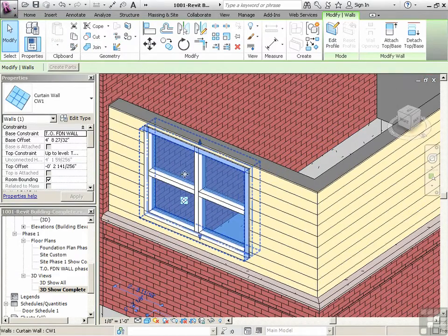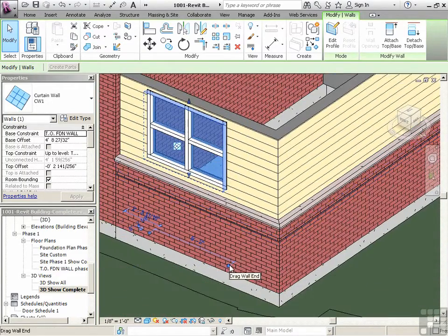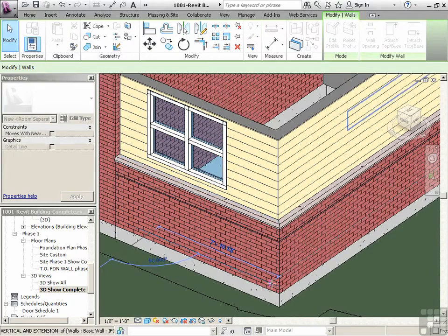Okay, so now it's starting to repeat itself. Now, the more that I look at this, the more I realize it looks like we're making a window here, and you've got to be a little bit careful. Curtain walls are not windows. You can use them to mock up quick windows, but they will not schedule as windows. So this is just going to schedule as a wall. So you've got to be a little bit cautious of using them overly like windows.